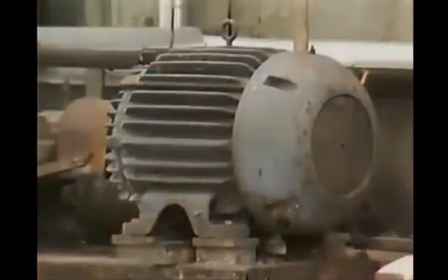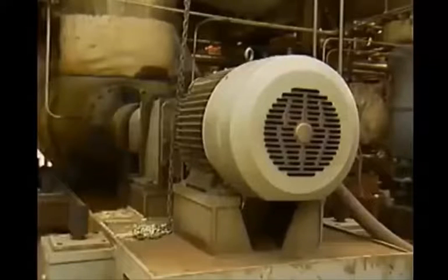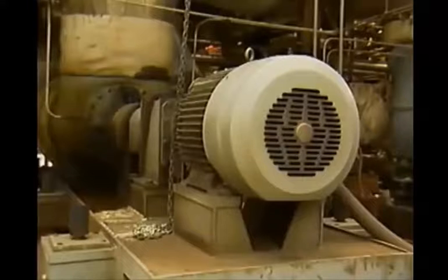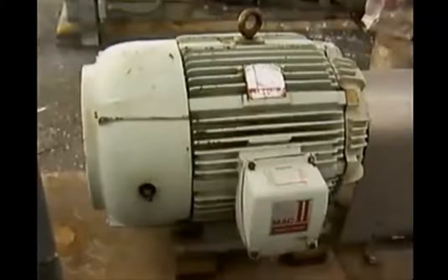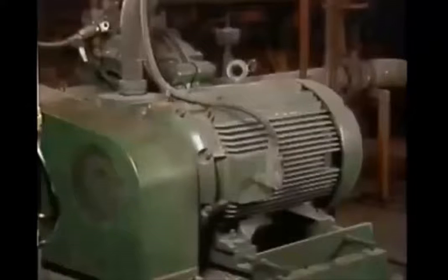Motors come in many different sizes and designs. The variations allow motors to be used in many different applications. Regardless of the particular design of a motor, however, the principle of operation is the same for all motors. That is, the rotor's magnetic field interacts with the stator's magnetic field, causing the rotor to rotate. Direct current, or DC, is current that flows in one direction. In a DC motor, direct current flows through a conductor and creates a magnetic field around the conductor.